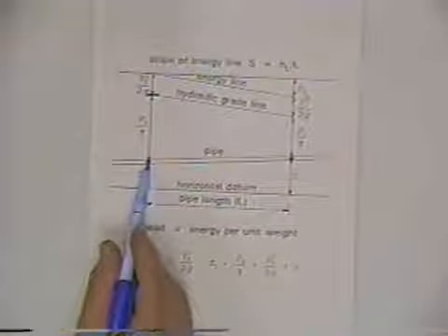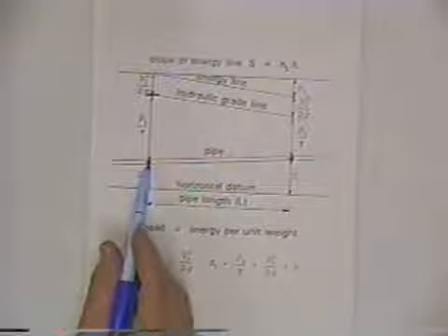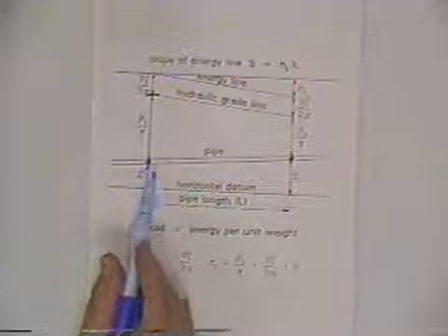And that's why we call it a pressure conduit, because it's not at atmospheric pressure. You don't have a free water surface at atmospheric pressure. You've got a confined flow situation where there's some pressure other than atmospheric. So that, by definition, is the hydraulic grade. Of course, we've got a hydraulic grade at any location, and if you connected the hydraulic grades at all the locations along a pipe or along a pressure conduit system, you get your hydraulic grade line.